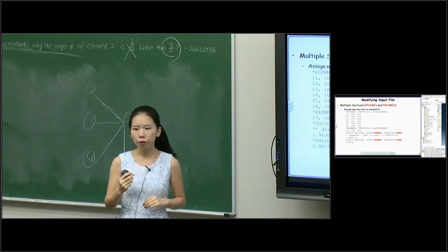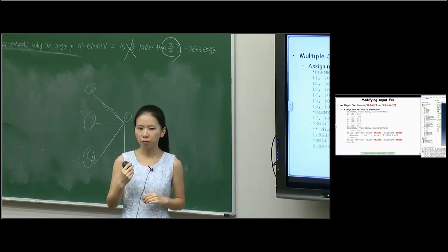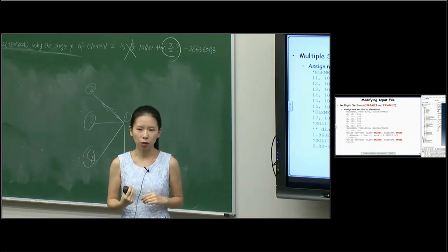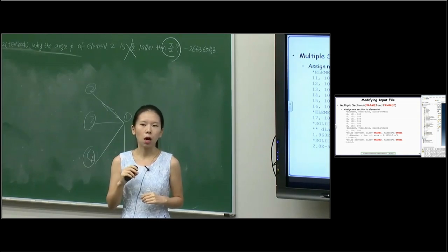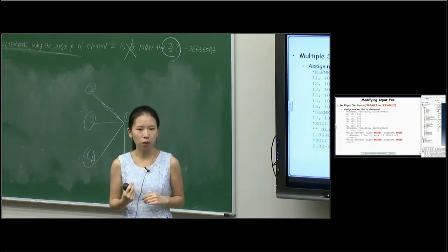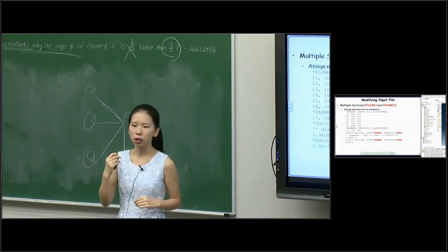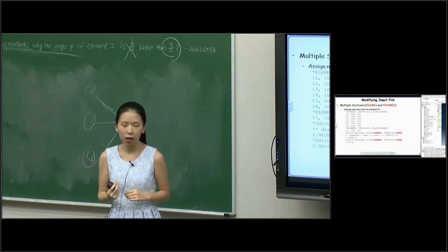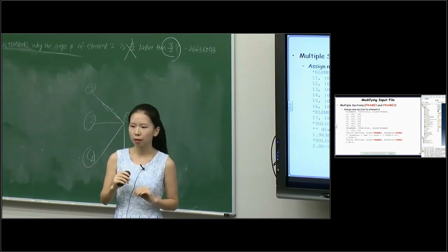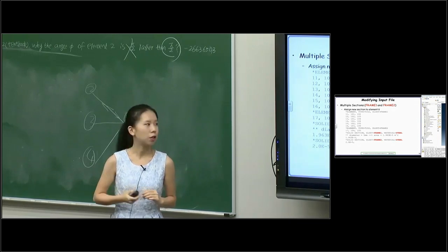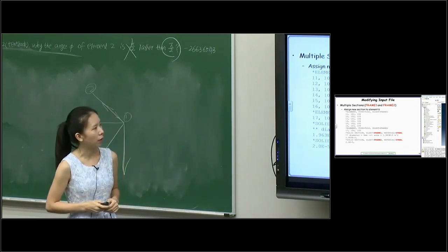For some member, if its stress is way lower than the allowable stress, what should I do? Decrease cross-section area, because our objective is to minimize weight, right? So when the member stress is very low, we decrease the cross-section area and then increase the stress and make it reach the allowable stress. And then we can get a fully stress design.